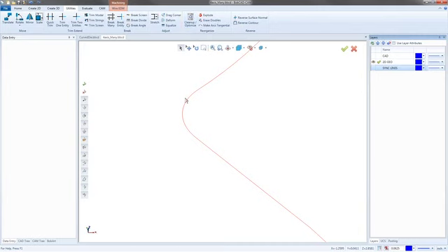I taught a class for a few years, and for the longest time, I didn't know that the Clean Up Optimize both cleaned up the geometry, so it rejoined my lines together. If I had a straight line that was broken into 5 segments, it rebuilds that, but it also gets rid of duplicates. So the erase doubles, you're only going to use if you don't want to rebuild your geometry. So if you're using the Clean Up Optimize, you're rebuilding geometry and getting rid of duplicates.